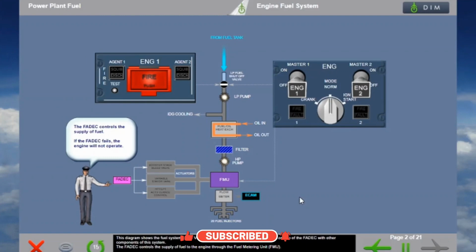This diagram shows the fuel system of the V2500 power plant, and you can see the relationship of the FADEC with other components of the system. The FADEC controls the supply of fuel to the engine through the fuel metering unit, FMU.